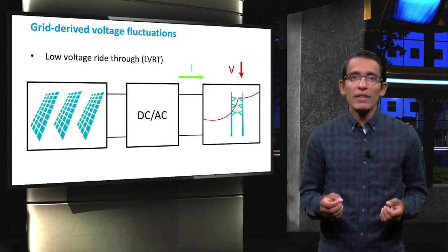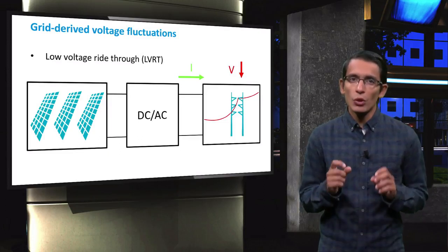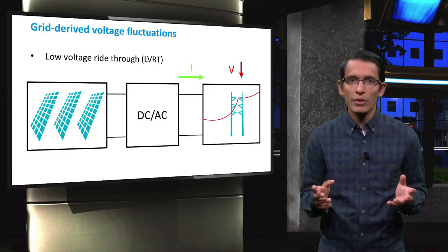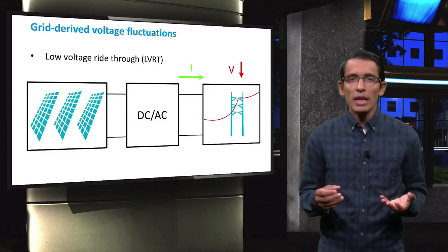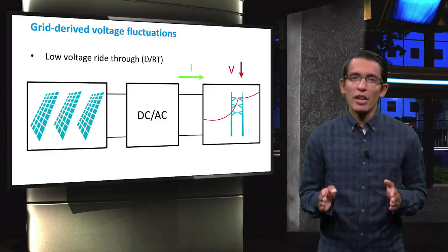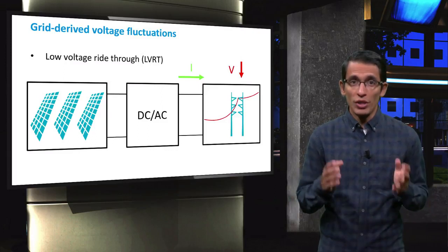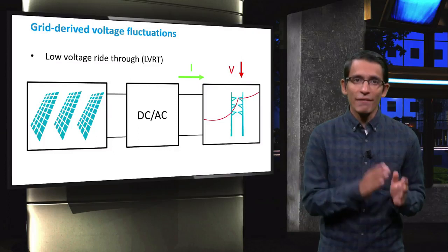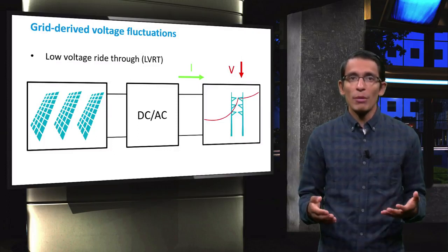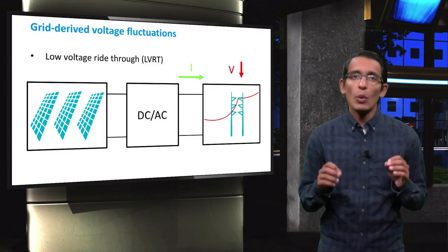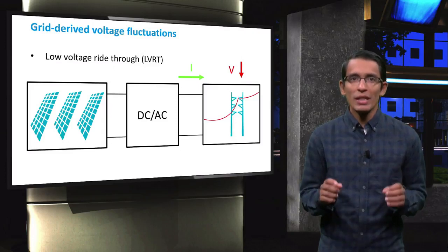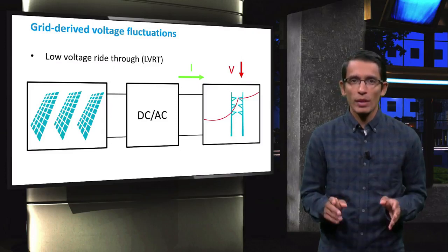This way, the PV is able to remain connected to the grid for short period voltage dips or brownouts. Without LVRT, a small grid fluctuation would then cause the PV to shut off. This in turn would cause a greater voltage dip, which would result in a cascading failure. Such a failure may result in a major blackout, so LVRT protection is essential to keeping grids healthy.